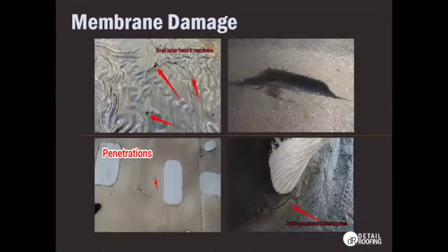Now, membrane damage is not necessarily indicative of your roof needing replacement. It could happen just because of natural shifts in the roof and weather fluctuations. Splits and cracks can occur, especially going from winter to spring months. Other things are just having contractors on the roof. They could be putting something down and not realizing that they're actually puncturing the membrane. Single ply roof systems are very susceptible to perforations, which can cause leaks just because they're so easily penetrated.